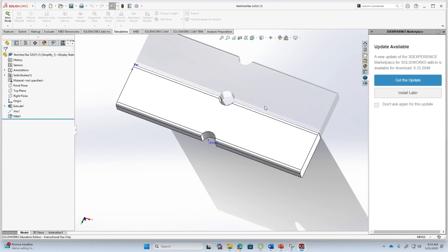So think about it. If you're trying to model a full aircraft, you cannot possibly model each and every component on it in a single analysis, right? So depending on what you are trying to get, it may be just possible to have a sort of a line sketch, 2D sketch sometimes, to get the first main information about stresses and strains. Then you can focus on certain areas where you want to focus and do more detailed analysis, okay.